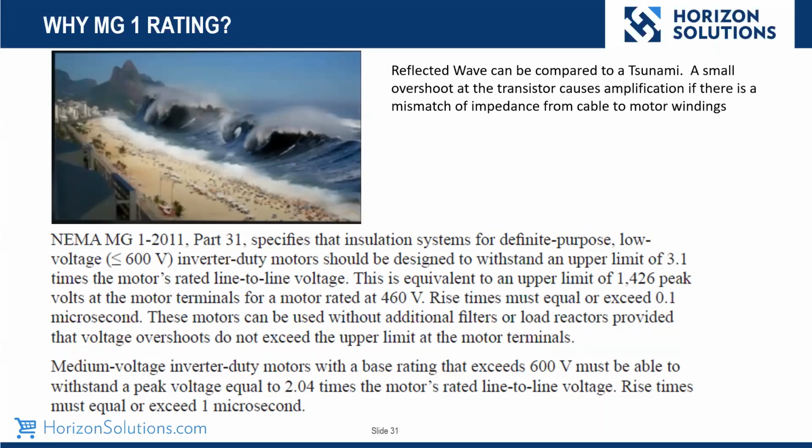And here we go. Here's a good example that you've probably physically seen on the news. It's sad news, but basically when you have a tsunami, a boulder falls over in the cliffs of Chile and starts a reflection across the Pacific Ocean. You have a long lead length with no impedance, and then it hits the beach. That's exactly what's happening when you're emitting from a VFD down the cabling.